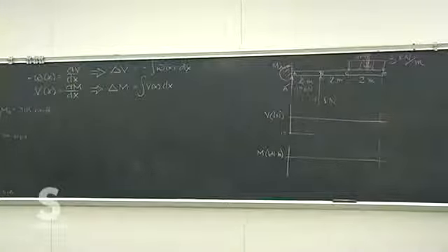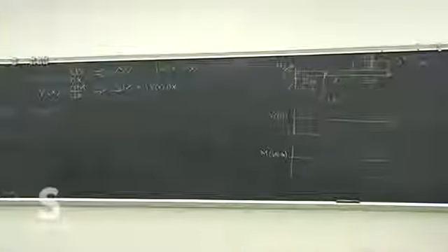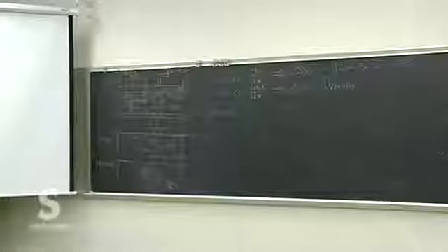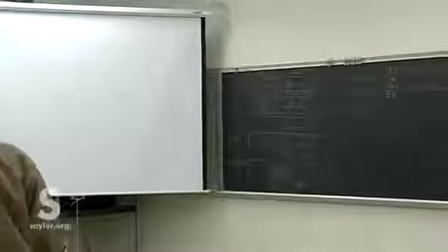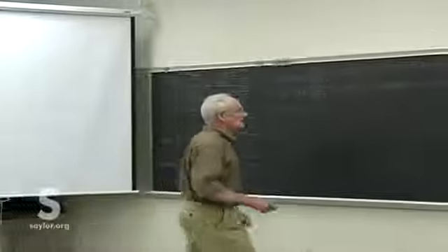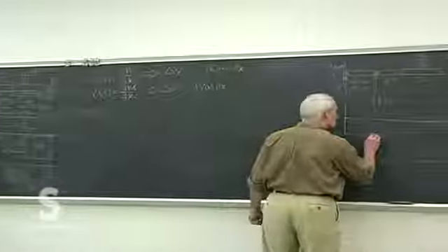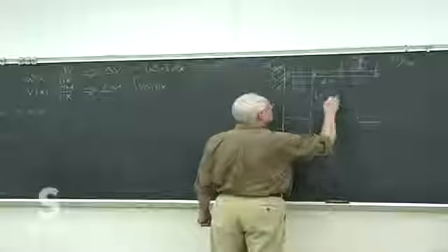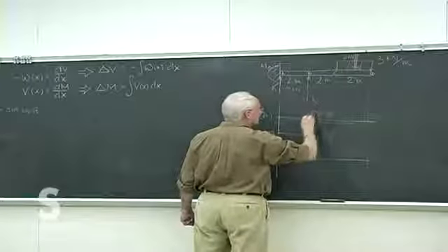Shear diagram is usually a lot easier because the jumps in the shear diagram go in the directions of the point loads, which helps a lot. Yeah, so most of you are getting that it jumps up from minus 13 to a plus 6. And then nothing happens in between.